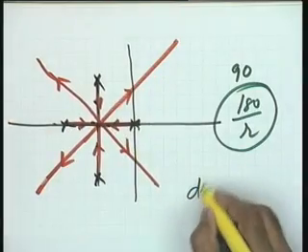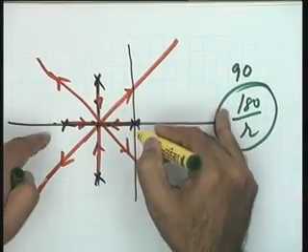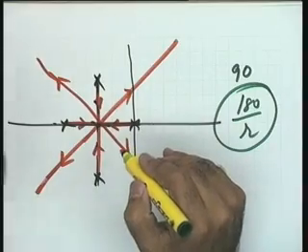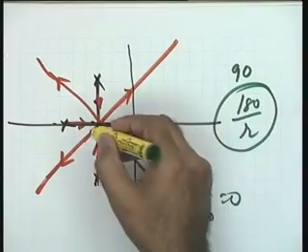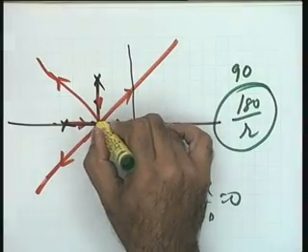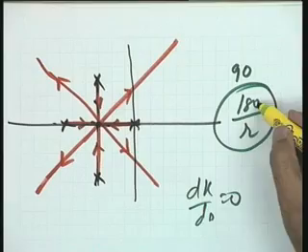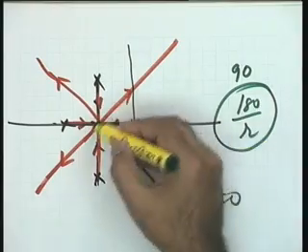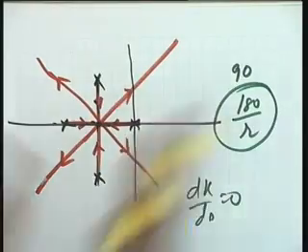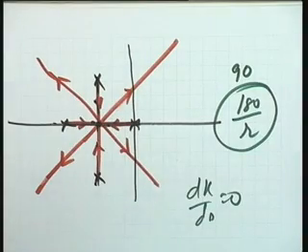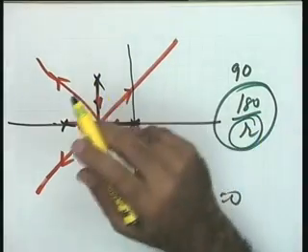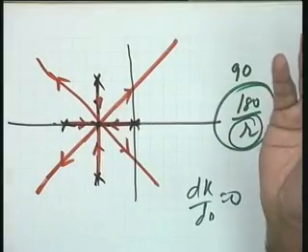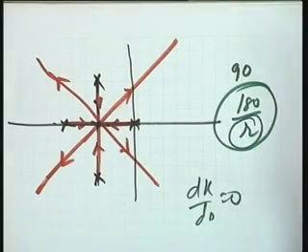If you solve your equation dk by ds is equal to 0 for this particular example, you will get only one valid breakaway point. All other points will not satisfy the angle criterion. So it means at this particular point there is a fourth order root of the characteristic equation, and now 180 divided by r is equal to 45 degrees, and therefore all these branches will leave this particular point at an angle of 45 degrees with respect to the real axis. So r is always even. Yes, it has to be. Come on, think of an odd situation. You probably cannot think of an odd situation because of the symmetry involved.